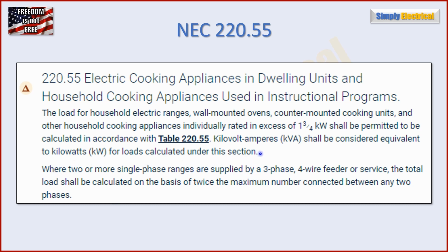So that last sentence there is pretty simple. It's just saying you can use kVA and kW interchangeably in these load calcs. We're going to save this second paragraph for later because it deals with 3-phase systems, and so we'll talk about that on its own for the last portion of the video.